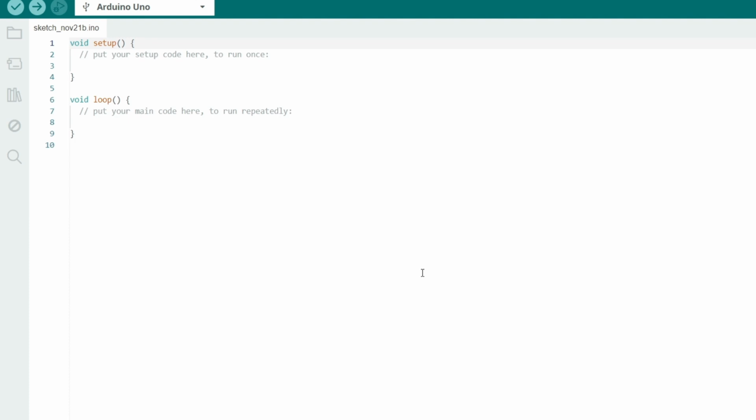If you wanted it to come on, you have to give the command for off. So with the analogWrite command, it's basically the same. If I wanted it to be 0, I'd have to set it to 255. If I wanted it to be 255, I'd have to set it to 0. And then it's the same for the in-between numbers too.